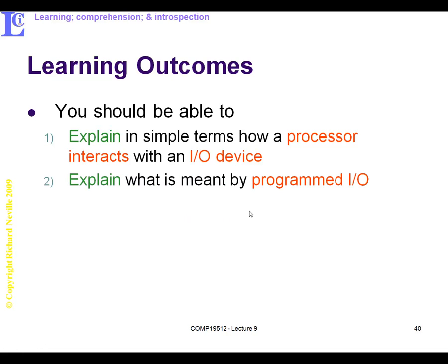And then we'll see one of the ways of interacting between I/O devices is to actually write a program to do it. Might not be that efficient, but we'll say that's a sequence of instructions that's setting up for the transfer of data between the processor and the I/O, the input-output device. So we'll talk about programmed I/O.